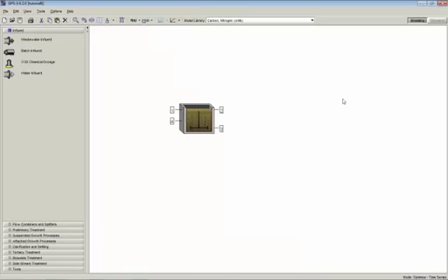So I go to my state variable menu, and you can see here that one's been checked off. This has already been set up for us. You can check off multiple target variables if you like, and your objective function will be calculated across several of those. But in this case, we're just going to use this one particular variable. We are going to try and get the readily biodegradable substrate concentration to fit as close as it can to the data that we have measured.